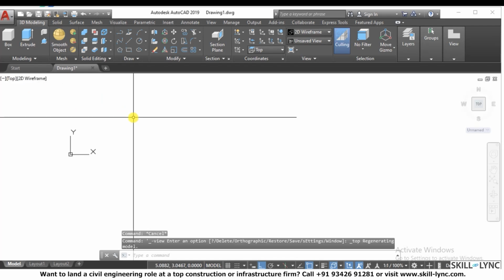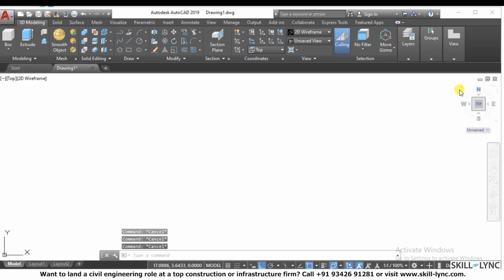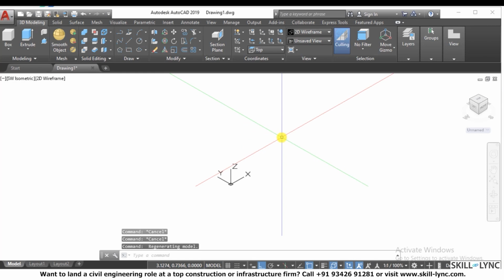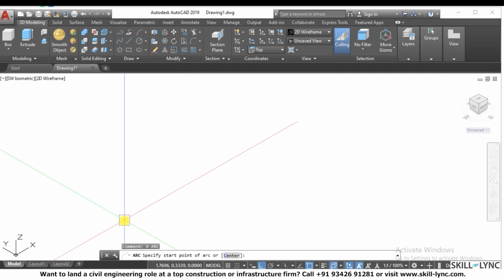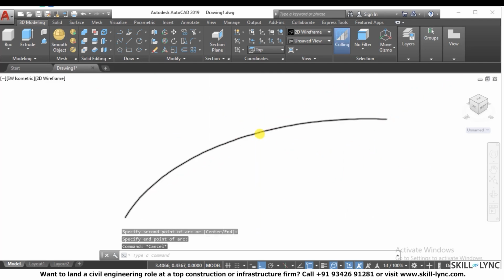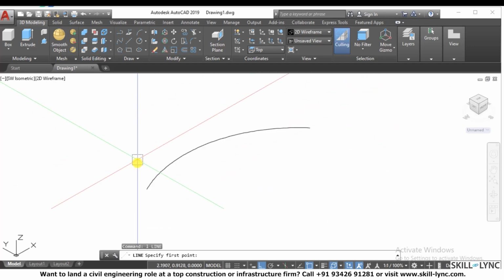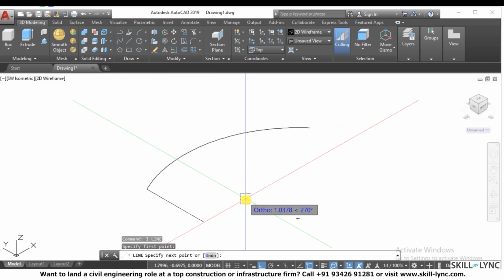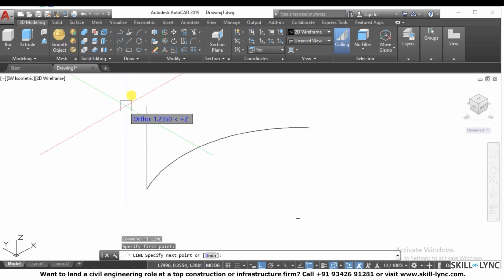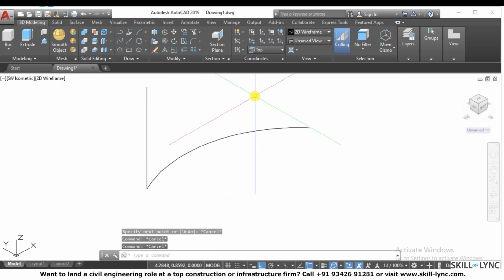And then we have, go to the top. The next is basically the tab surf. Now the tab surf command. So this is called a tabulated surface, not surface tabulation, tabulated surface. Now how it works, if you have an arc and there is a line which is a perpendicular vector going in the z axis, so you can do it by direct entry, just clicking the z axis. In the ortho you can go in x, y and in z. So let's say I'm going in the z direction.